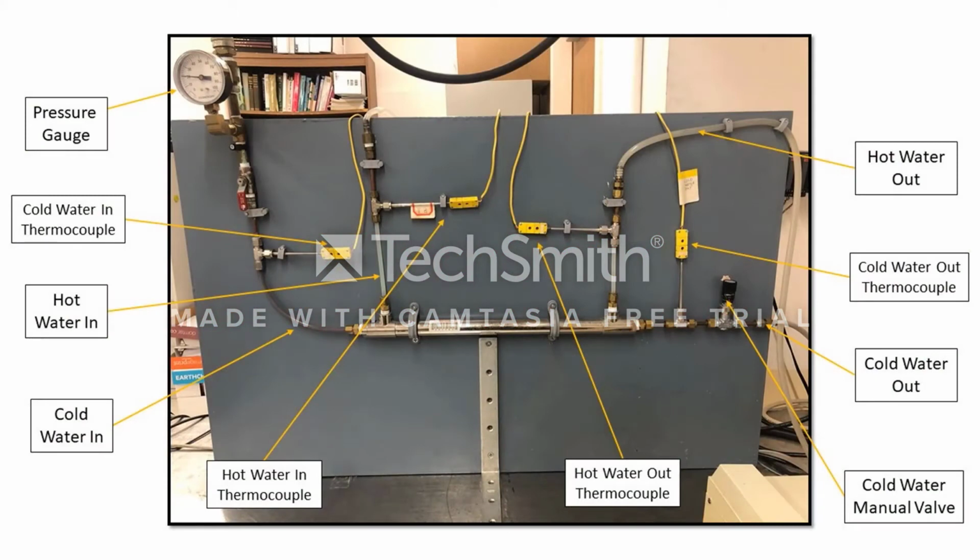Alright, for our last activity, we are going to be performing regulatory experiments on the 3 tuning sets that we found previously doing automatic tuning. Now, just as a reminder, a regulatory experiment is when we keep the set point constant and we add a disturbance to see how the system will react. Now, again, we are going to be doing this for each of the tuning sets that we found previously, including slow, normal, and fast.